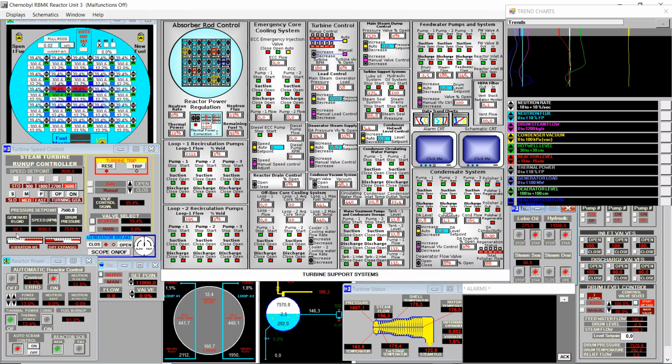Generated load went up to 60 suddenly, but I guess it will stabilize back to some other value. So we already disconnected 2 of the 3 feed water pumps, turbine in the startup valve, level control 1 element and startup valve. So we did everything we needed to disconnect the generator. Now I will continue reducing the set point to 10%.